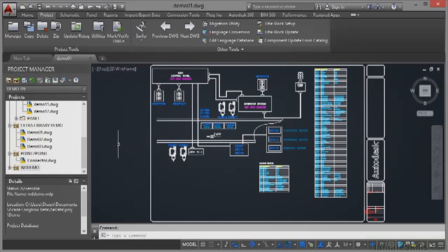But that's how you set up a new project. So you give it a name, set up the location for it. AutoCAD Electrical will make sure that you've got all the appropriate WDP settings set up. As you go through that process for the new project, you're setting up your new WDP file. So that's how you can set up a new project, even though I've already copied to create a new project, if you see where I'm coming from.